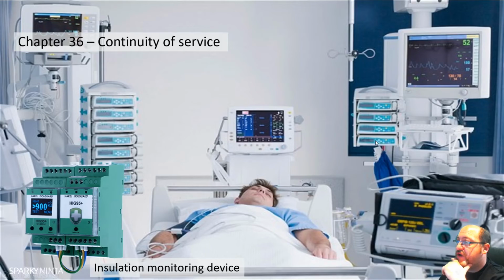And lastly, 36, continuity of service. Now, obviously, depending on the environment, this might be a medical location, this might be a data center, so there could be two issues here. Medical location, continuity of service, it's obvious. If you lose power, IT equipment maybe needs to have an installation monitoring device to raise an alarm. If you have a data center, you may have a residual current monitor or an installation monitoring device to, again, raise an alarm. What you want is a single fault condition to stay in service but have an alarm system in place. This introduces the IT system, which we'll talk about later on.